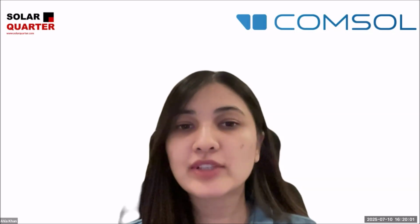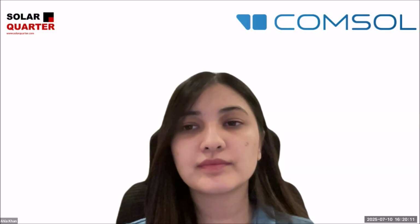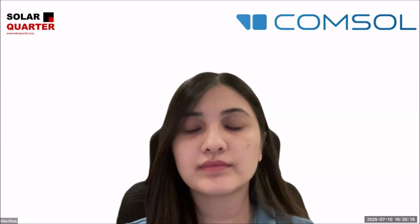Thank you. Next question is, are non-linear magnetic materials supported? Yes, as I mentioned already, nonlinear magnetic materials are supported. We have an extensive material library where some of the nonlinear behavior is already accounted for. But let us say you have conducted an experiment on a material, and you have particular material property variations as well. In that case, you can utilize that data, give it in the material property section, and model it as well.